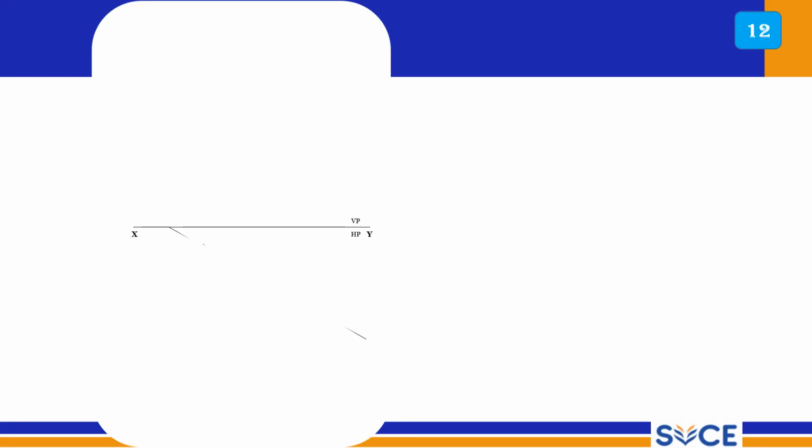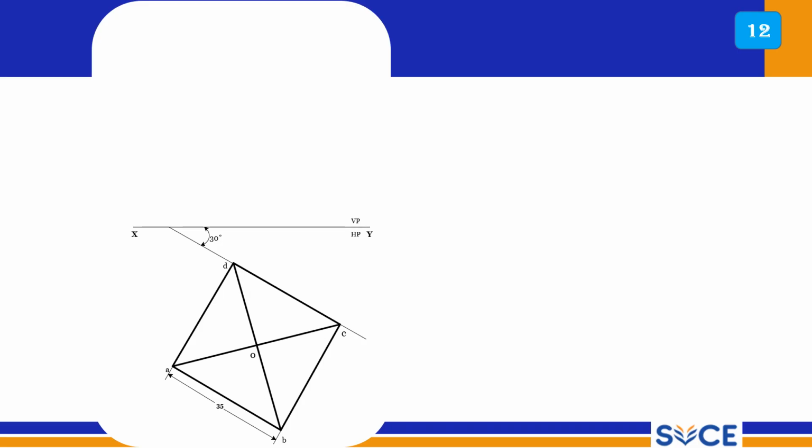So this is the simple front view and top view, right. The orientation is very important. One of its base edges is making 30 degrees to VP, right. Draw its simple front view. So here, to draw simple front view, none of the slant edges are parallel to VP. So I am turning this OA parallel to VP, and then I am projecting here, right.